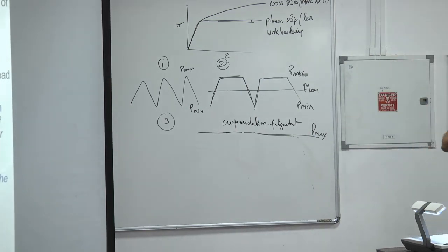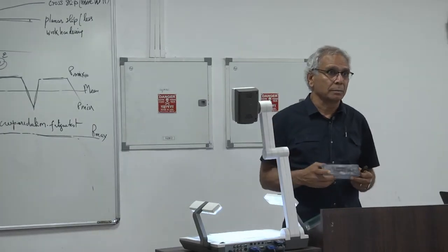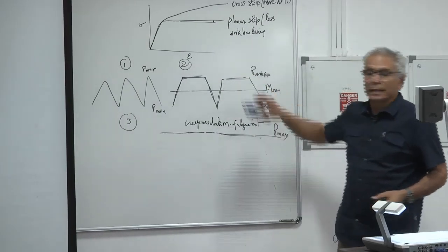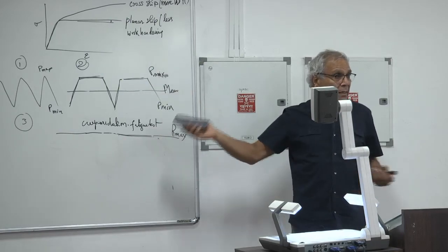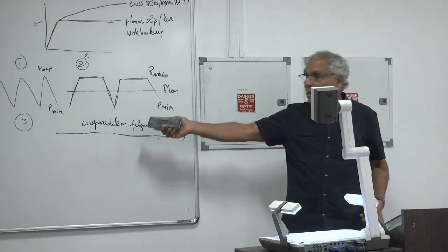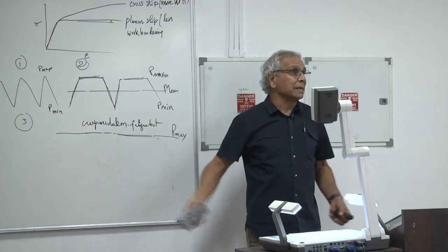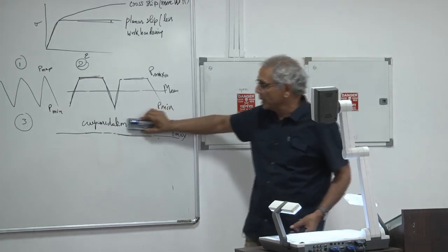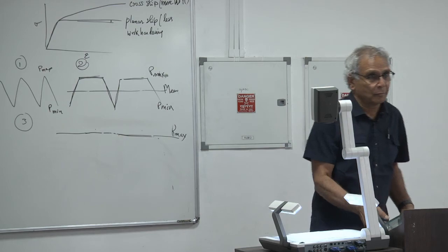So again, these are little complications in the whole business. So if this is a nickel-based superalloy, and you're doing this test at a high temperature where there's a possibility for oxidation, there's a possibility for creep also, but not necessarily dwell fatigue in this sense, then you may be doing a creep fatigue test or a creep fatigue oxidation test.